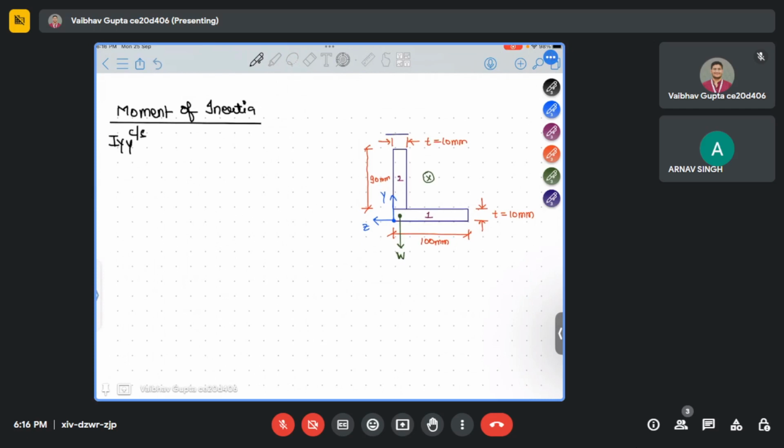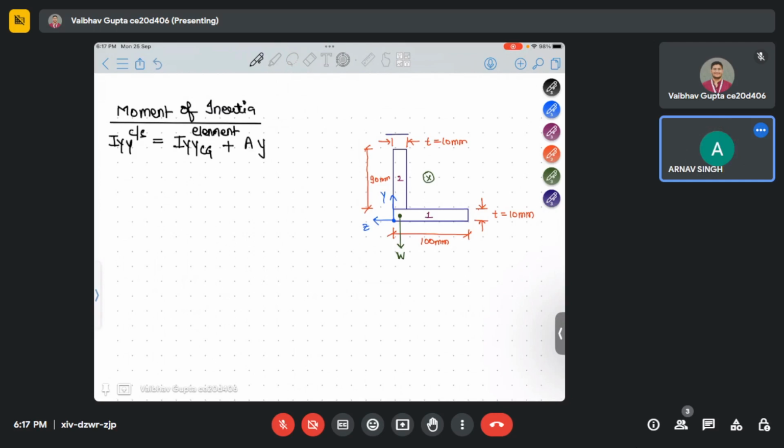Iyy of the cross section is equal to Iyy of the element along its CG plus A times (y minus y naught) squared. Yes, this is the parallel axis theorem. So Iyy of the cross section will be equal to...